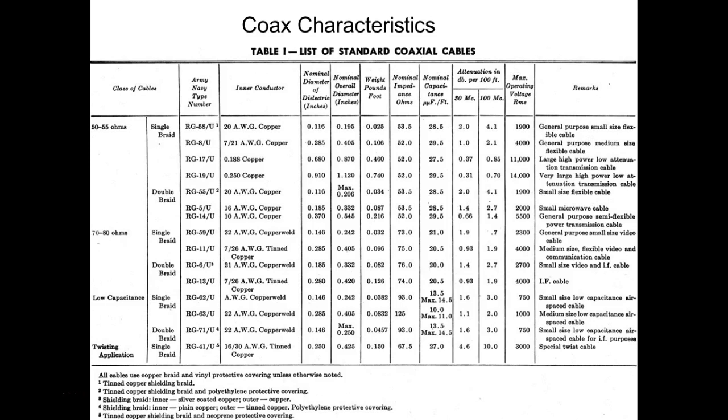What we ran is a 300 ohm cable down to our TV, and then we put that in the back of our TV. It was a duplex cable, but it was really neat because the two conductors were out, and then it had an insulator in between, which was real flat. And then, of course, the spacing between these actually established the 300 ohms of impedance.